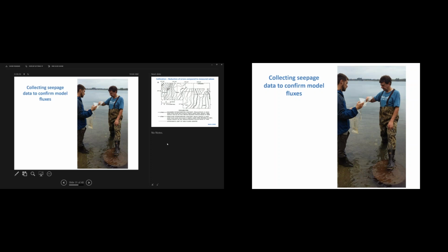That's really coarse material and stuff. So there's no way you can model that 14-foot head difference and put your permeability of sand in there and expect not to have a huge torrent of groundwater going through. So something had to add up, and that's why our model didn't work. So we went out and got more data to try and figure out what's going on.